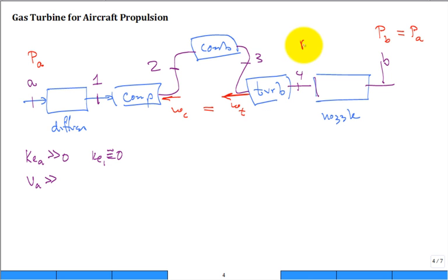So there you go. Now, let's ask this. What about the pressure at 4? How does that compare to the pressure at B? Well, I have to know a little bit about how a nozzle works. Is the pressure at 4 greater, the same, or less than the pressure at B? It's greater. And think about how you analyze the nozzle. Isn't the higher pressure at 4 better for the nozzle? Won't it make the gases come out faster? It will. And we see that in our calculations.